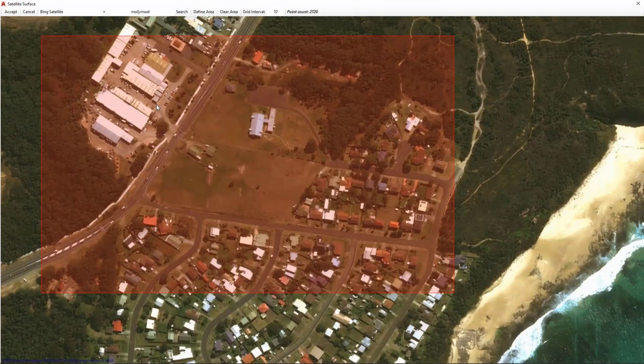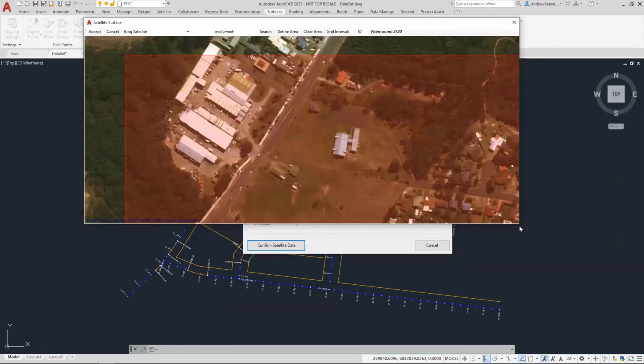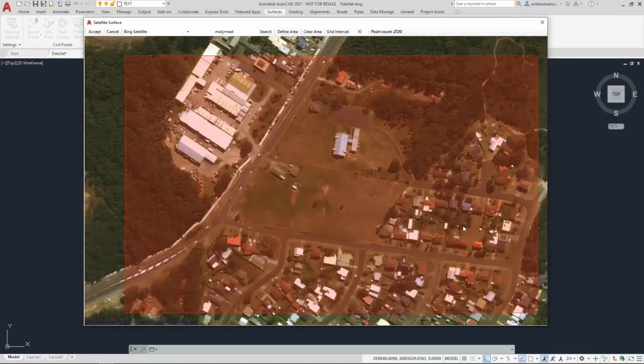So as I mentioned, we have improved the quality of the imagery now. So we'll actually download at the highest quality. Now, in regards to the imagery, what we see is what we get. So at the moment, I'm going to also download the imagery for all of this. Another thing we added actually was this little image buffer, which I'll explain why later, but we actually download a little bit more image to the top and to the left there. So if I wanted to basically control the extent of the image downloaded, I just move the window and drag it around. So as long as I cover that red area, I've got enough aerial imagery.